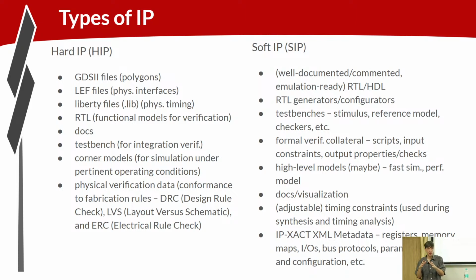There's a certain API to interface with the logic that you're delivering, certain constraints on what the customer should be allowed to provide as inputs. You want to deliver the properties that provide those constraints. Those properties are used in two ways. First of all, they verify that the customer's surrounding logic is behaving, and then they're also used as assumptions for the verification of the IP itself.